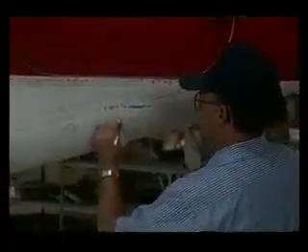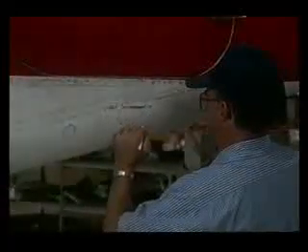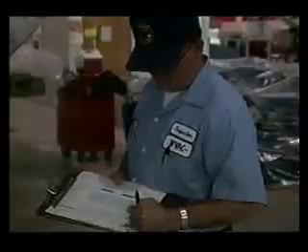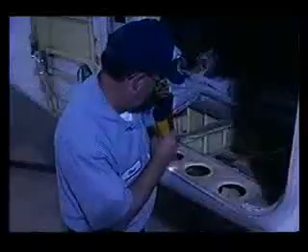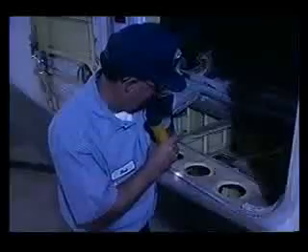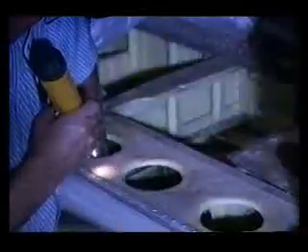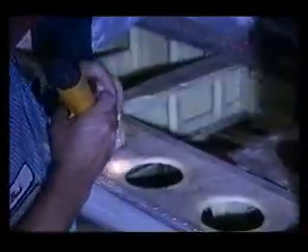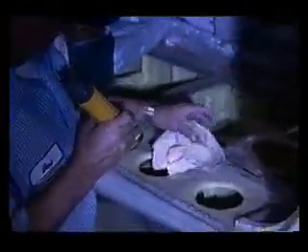Level 1 corrosion is the least severe stage of corrosion. Level 1 corrosion is defined as local, generally light corrosion which can be blended out or reworked within the manufacturer's limits. Even if corrosion damage requires a repair which exceeds the manufacturer's limits, if this is a result of continuous light corrosion repairs, it should still be considered Level 1 corrosion. And finally, if local corrosion can be linked to a single unusual event, such as a fire or chemical spill, it should still be considered Level 1 corrosion.